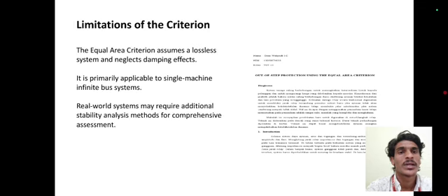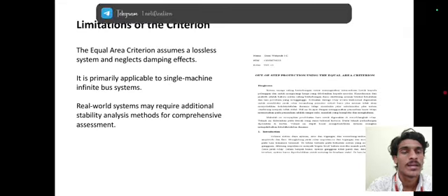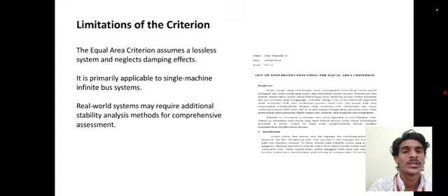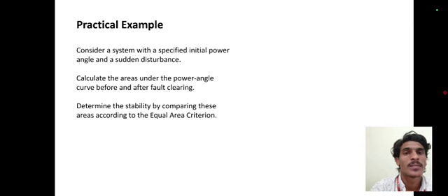Limitations and criteria. The equal area criterion assumes a lossless system and neglects damping effects. It is primarily applicable to single machine infinite bus systems. Real world systems may require additional stability analysis methods for comprehensive assessment.